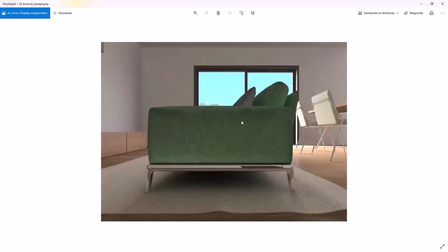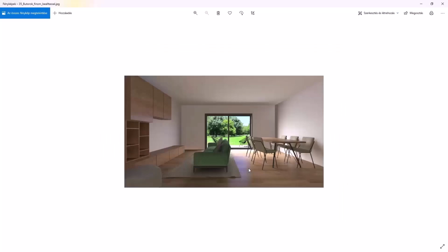In the second phase, we worked on the furniture. We also set the render style for these and then fine-tuned the materials. The third phase was to adjust the decorative elements materials. We have separated the lamps and the decorations. First, we activated the lamps layer and created a render without the artificial lights. We saw that there were some dark areas, so we turned up the lights on the next render. These illuminate the darker areas nicely.